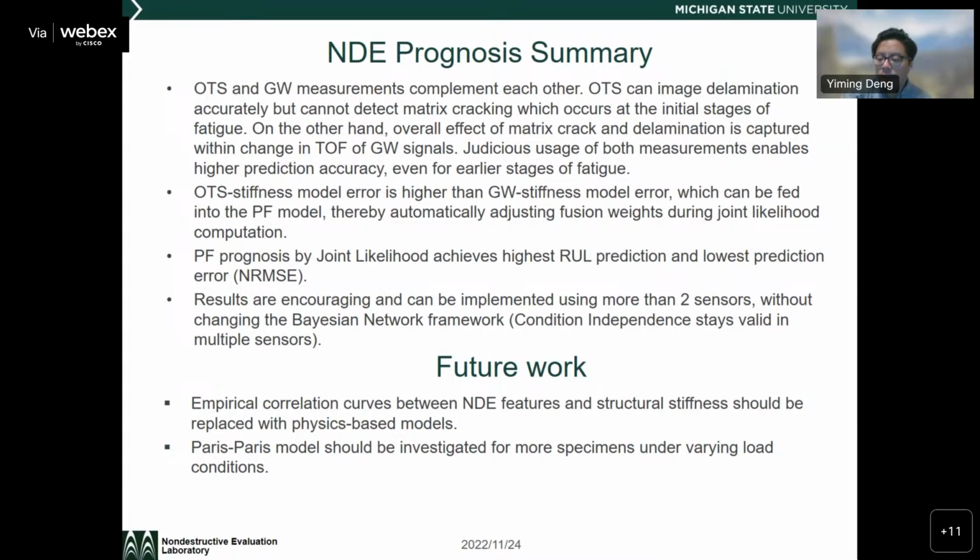For different materials, in this case a complex composite, we need to develop a good damage growth model. In order to estimate the damage growth model parameters theta, a Bayesian updating scheme is proposed, where we can get new data from any measurements to update the estimation of the posterior probability over time.